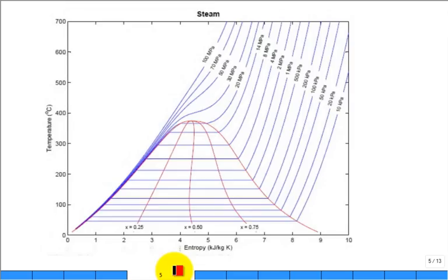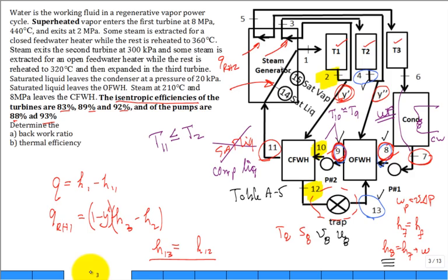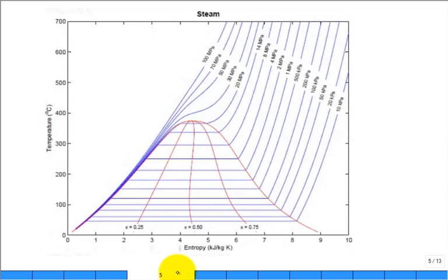What we're going to do is come back and put this cycle on this diagram, okay? But sir, no matter how many turbines or pumps you have, the back work ratio is the summation of pumps over the turbines? Right, make sure it's all on a per unit mass basis, the same. So the sum of all the pumps divided by the sum of all the turbines. And with each mass flow going through that? Yeah, you have to correct back to a common mass flow rate.